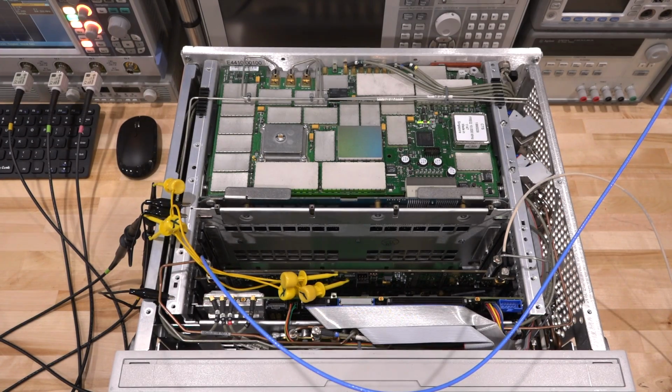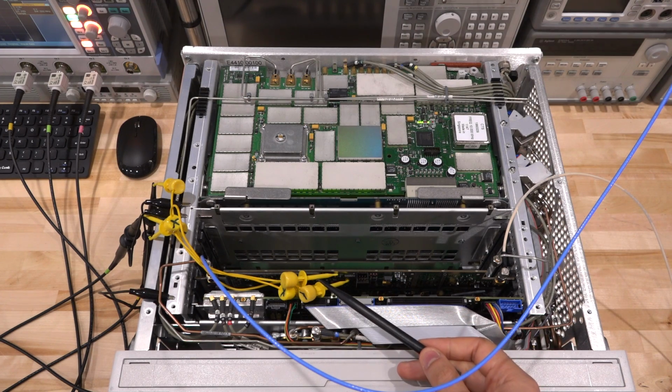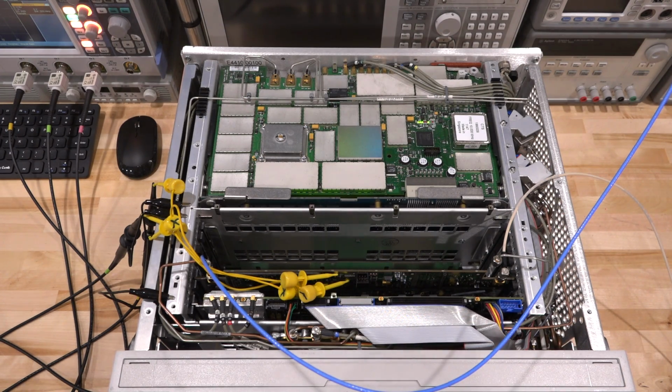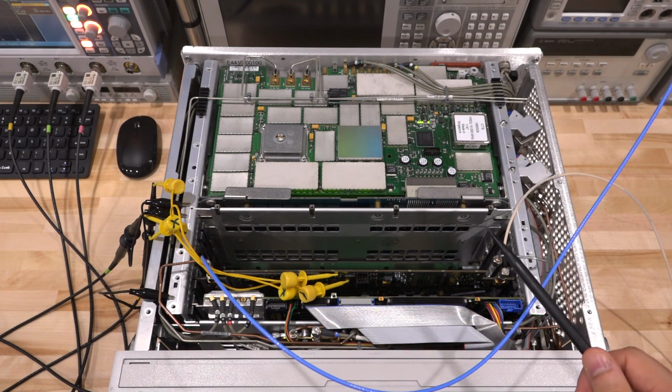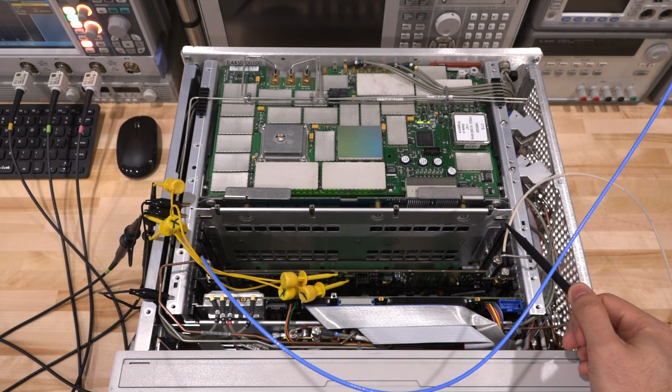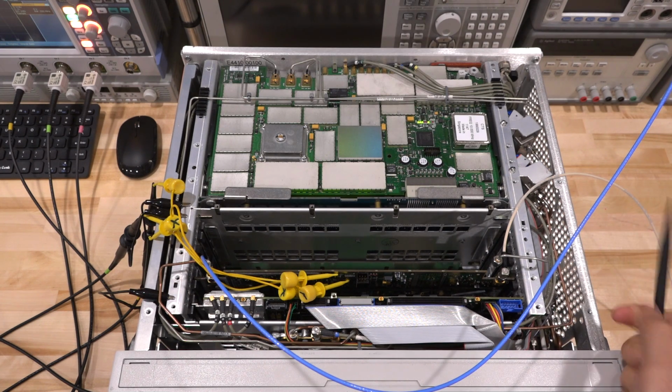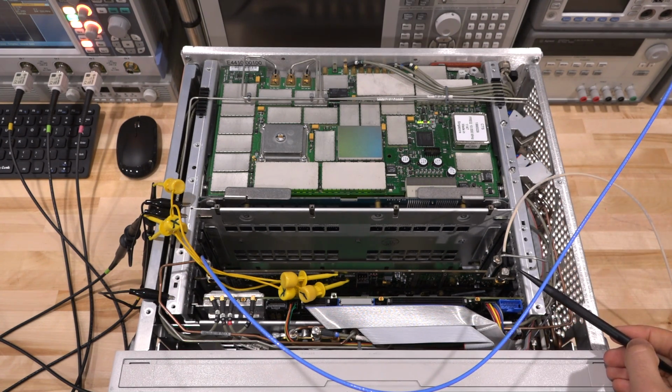Okay, let's take a look at our setup here. So I've made a couple of changes. First of all, I'm taking the 3 signals I talked about out, and they're going onto the Rohde & Schwarz RTO2064. I'll show you that in just a second. I'm also taking the output of the LO Synthesizer here, and that goes into the Keysight MXA so we can monitor it. The input no longer comes from the instrument itself. I'm providing my own 4.8 GHz signal directly into this connector from another source. It's an Agilent EXG, and that allows me to change the source in power and in frequency.